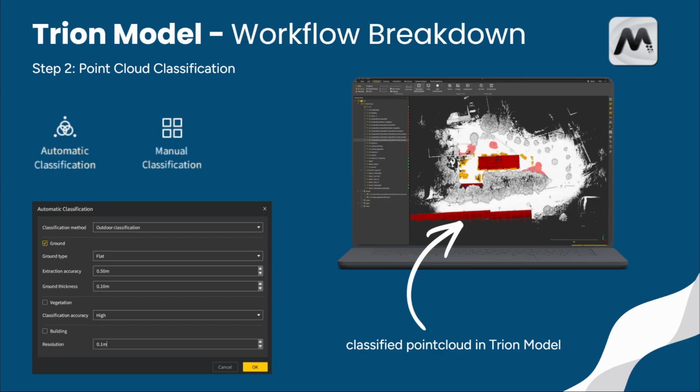Of course, no algorithm is perfect in every situation. So the next step is to review the result carefully. Using manual classification, we can correct and refine points that were classified incorrectly. In addition, we can use different clipping tools to manually remove any points that do not belong to the terrain surface.